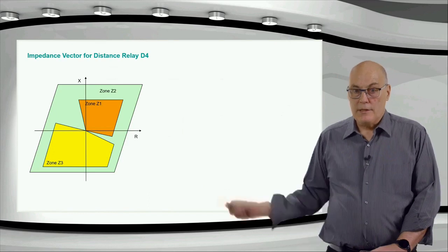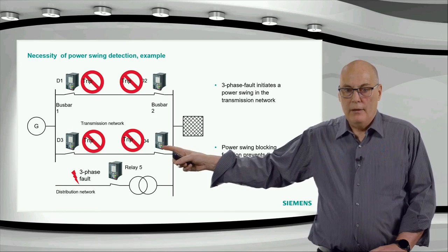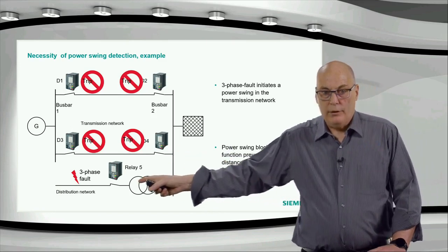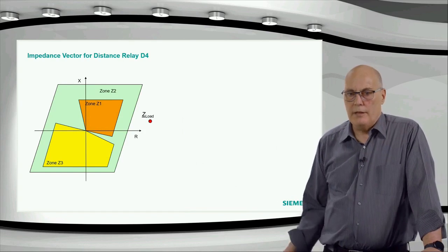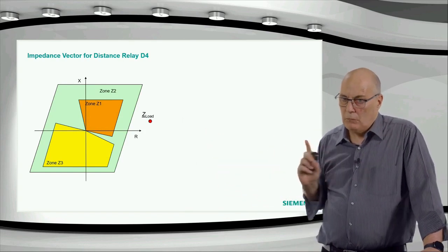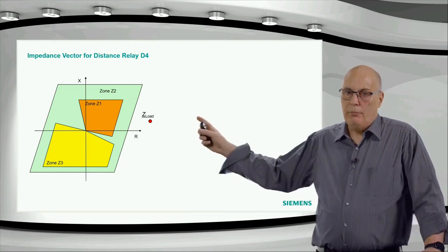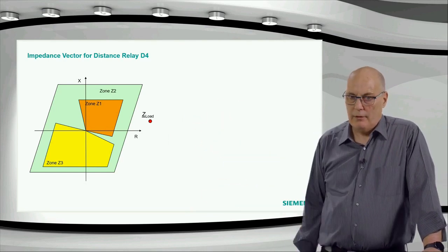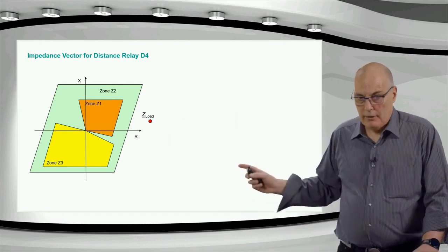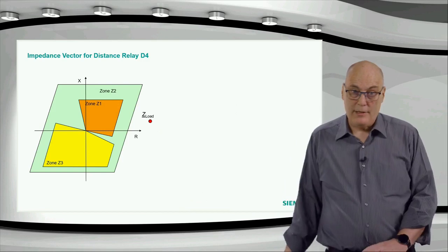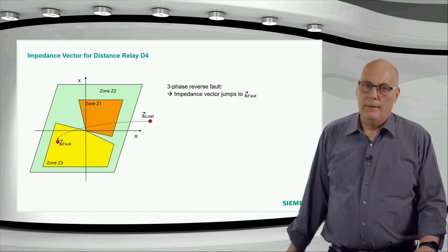And here you can see this is the D4 relay. Okay, we can maybe go back. See, D4 was the relay over here. This relay sees obviously that fault in reverse direction, is what you will see now. You see there's a load condition transferred. So D4 is actually not quite, the load would have been on the other side. Sorry about that, I think the diagram is not that accurate. So as far as I remember, the load did come in from the left-hand side, right-hand side, but it's just a symbolic diagram, this one.